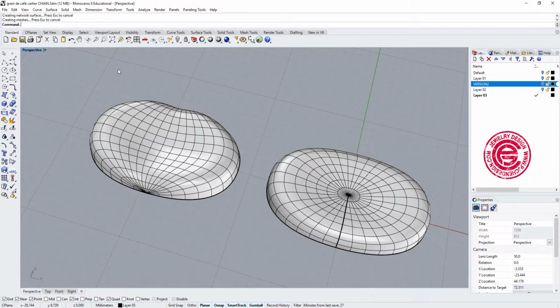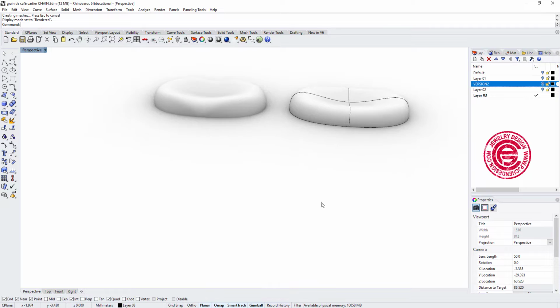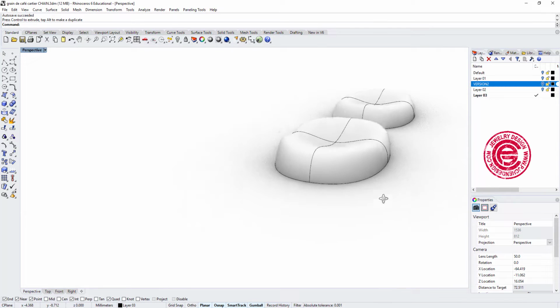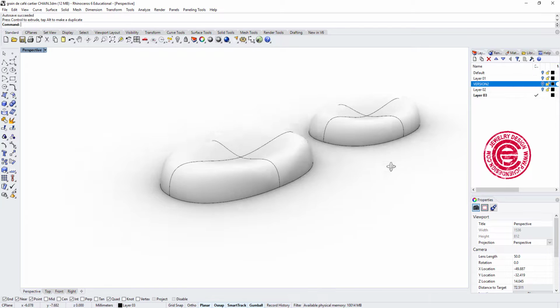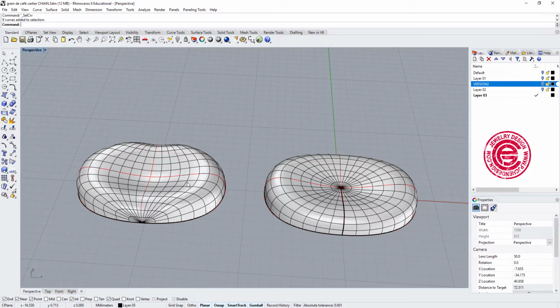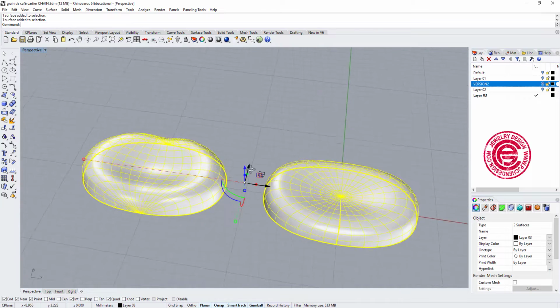And notice that with the same command, because the curves are different, the surface is different. Let's take a look at this one. You're going to notice in the render view, the one that we worked with using the first curve network seems to have a kink or a point on the surface. The reason for that is that the way of creating the surface has a different direction, moving the surface to the top.